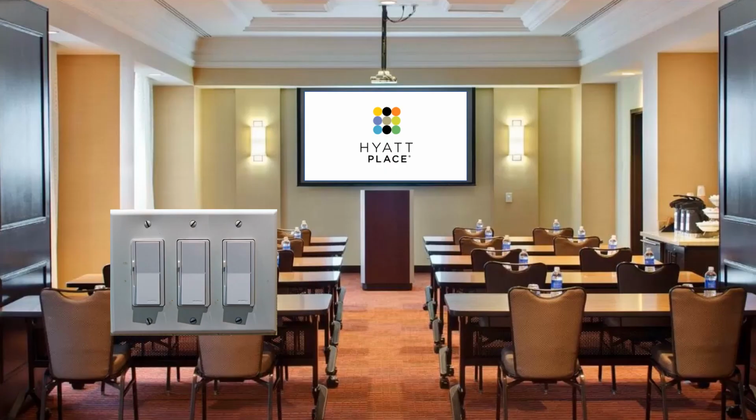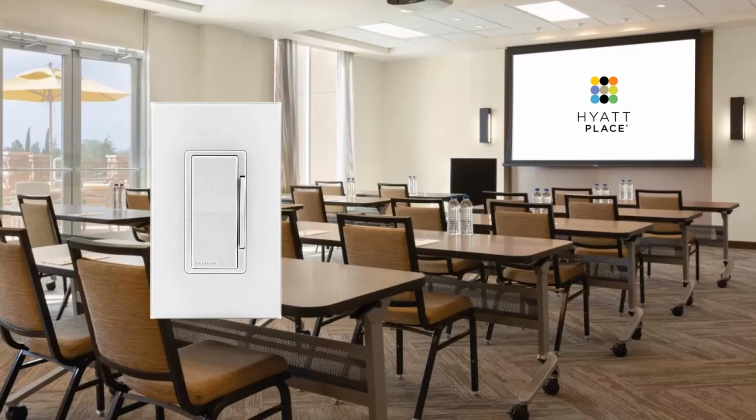In individual meeting rooms where downlights, wall sconces, ceiling cove, or pendant lighting fixtures might be employed, wall box dimmers will be provided. These dimmers allow for the individual adjustment of the different fixture types which exist in the room. These simple-to-operate dimmers can be adjusted by pressing the top or bottom of the illumination level control bar on the side of the unit. The lights can be turned off and on using the paddle push button. Lights will fade up to the last level on the illumination level control bar, and further adjustments can be made using the same control bar.